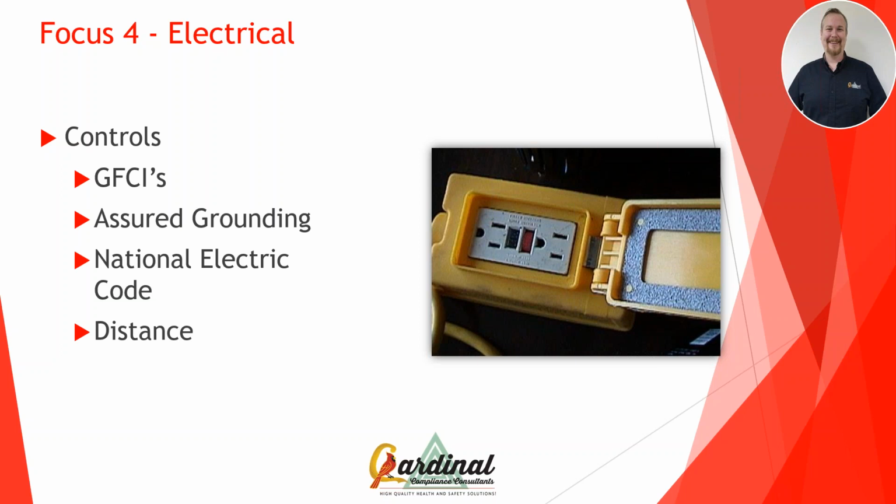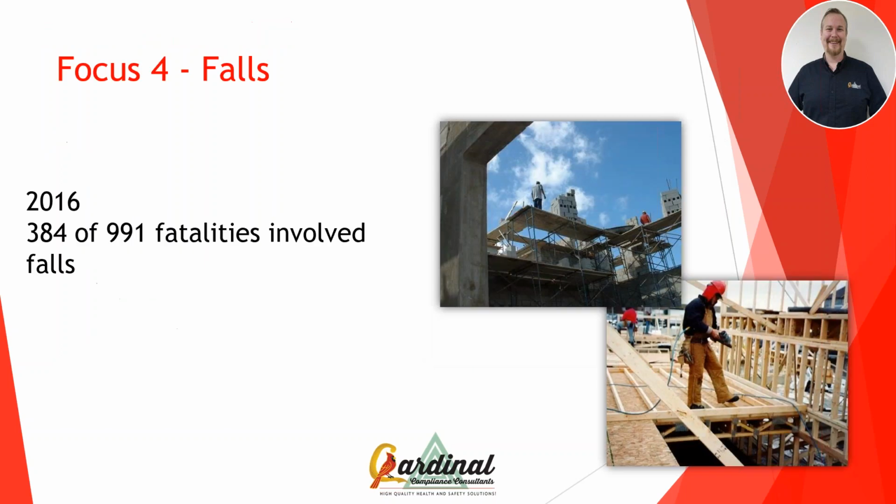Now, when it comes to poor wiring, the National Electric Code, that's the standard that electricians are going to follow. That being said, this is why it's important to have qualified electricians do your electrical work and any type of repair you have on electric tools. And then finally, distance. When you're working with a power line, the further you are away, the less likely it's going to arc. So just consider these things with any electrical hazards you may be exposed to on your job site.